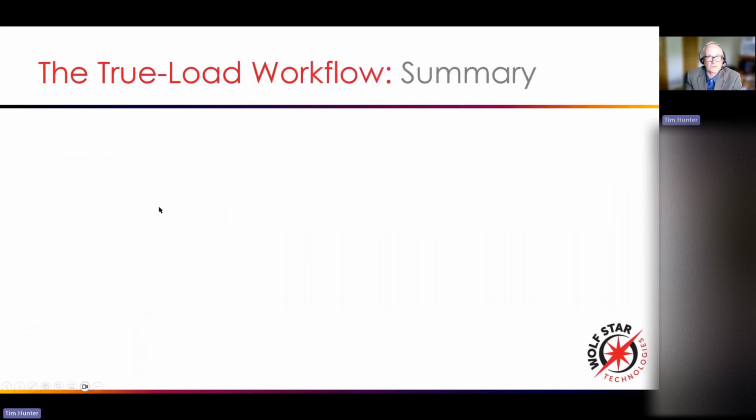So we're going to do one more run through on the workflow, just one more summary slide on how the workflow works. Basically, again, we're starting off with an FEA model, your FEA model, but rather than putting in complex loads, you're going to put in a series of unit load cases, however you want. So, 1 kilonewton XYZ, maybe a pressure load, maybe a thermal load, maybe an inertial load. However you think the load is coming into your structure, you're going to model that in FEA.